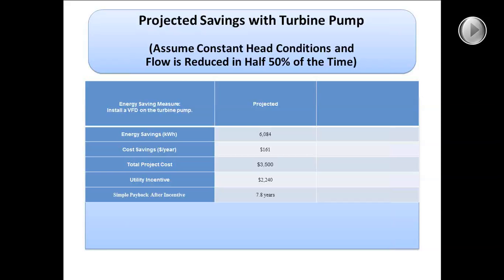And that's the case a lot of times. If you're looking at reduction in flow to have a centrifugal pump, VFD doesn't usually make sense. With the turbine pump, it's more economically feasible.